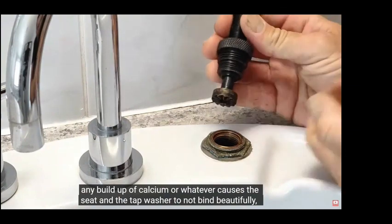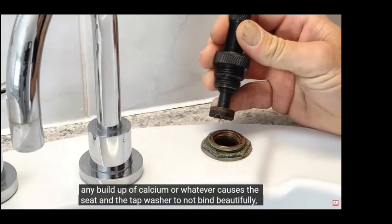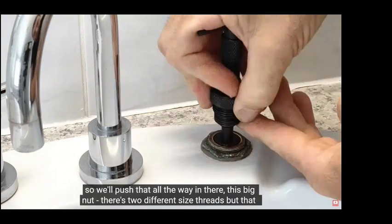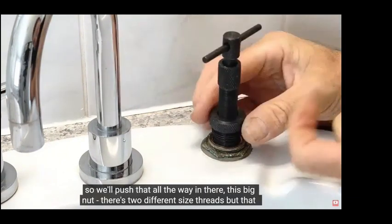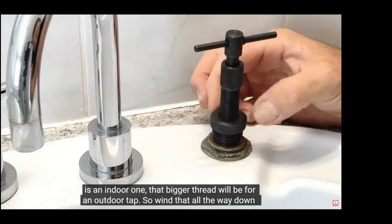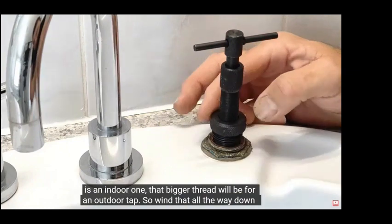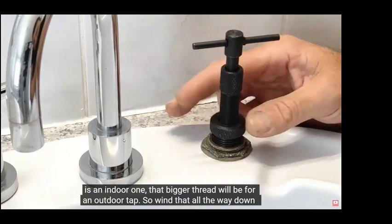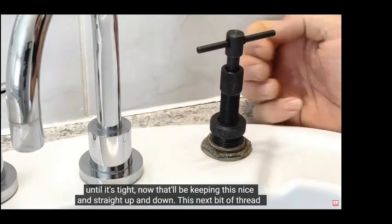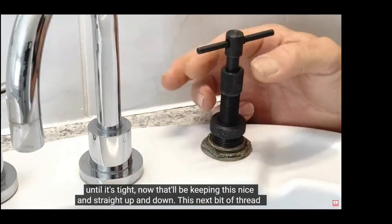If there's nothing wrong with it, don't touch it. Don't go near it. If it's all fine, even if it doesn't look shiny, it doesn't have to be shiny. Just try a torch down there, flush it out with water, stick your finger over it, make sure there's no gaps. If you're not sure, you can very lightly skim it with a resetting tool. If it comes up shiny and smooth all the way around with no grooves, you've done it.